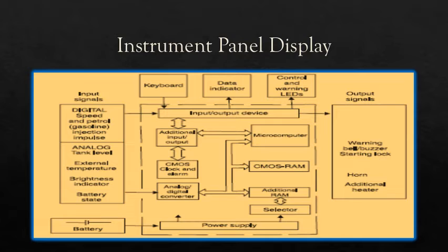Newer car versions incorporate instrument clusters with microprocessors which can perform advanced functions. The processor carries out the entire signal processing. Conventional needle-based displays have been largely retained, given the familiarity and convenience for old school car users. Stepper motors are used to rotate the needle in these meters, but some bold modern car manufacturers have stepped out of this line of thinking and replaced the displays partially or completely with liquid crystal display based digital displays, depending on the function being incorporated.